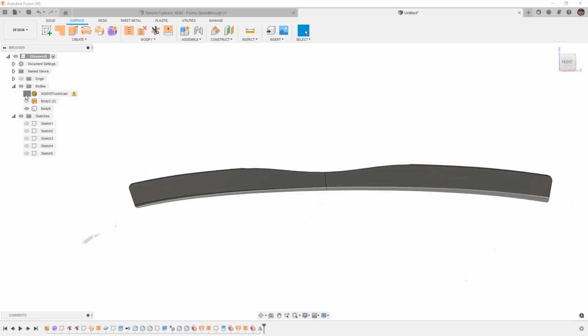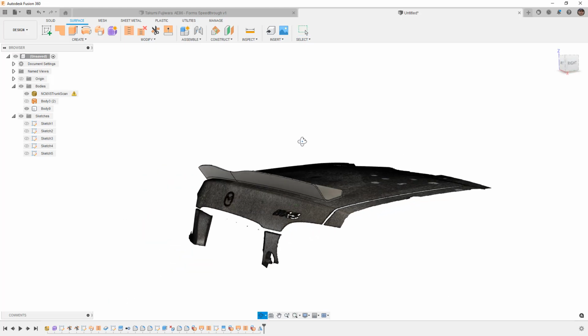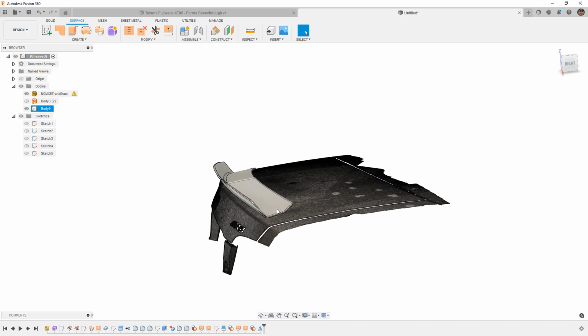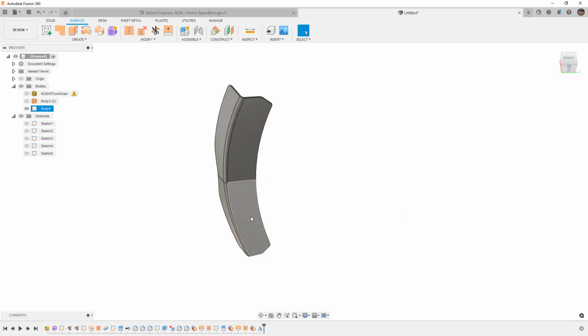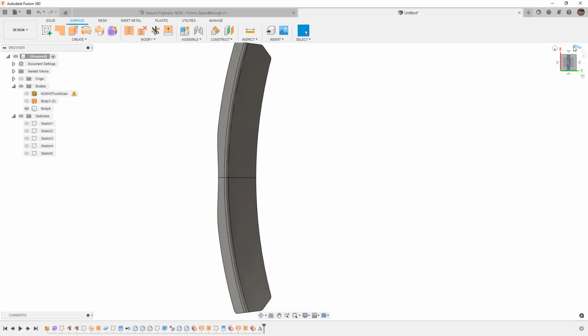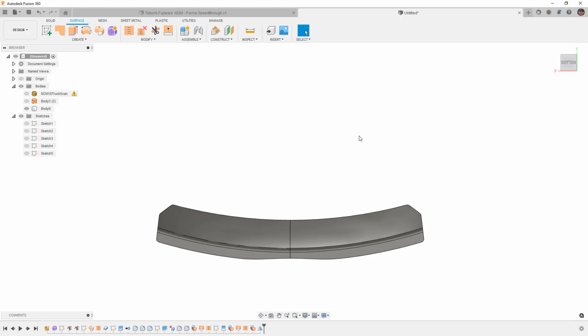The last bit to this really comes down to the details. So this right now would be able to adhere with something like a double-sided tape. Typically when this is done, what you see is there'll be little recesses for tape to go in. Otherwise, it's going to raise it up the thickness of the tape. So if you're using something like a 3M VHB tape, which is typically what's used for stick-on body kits.